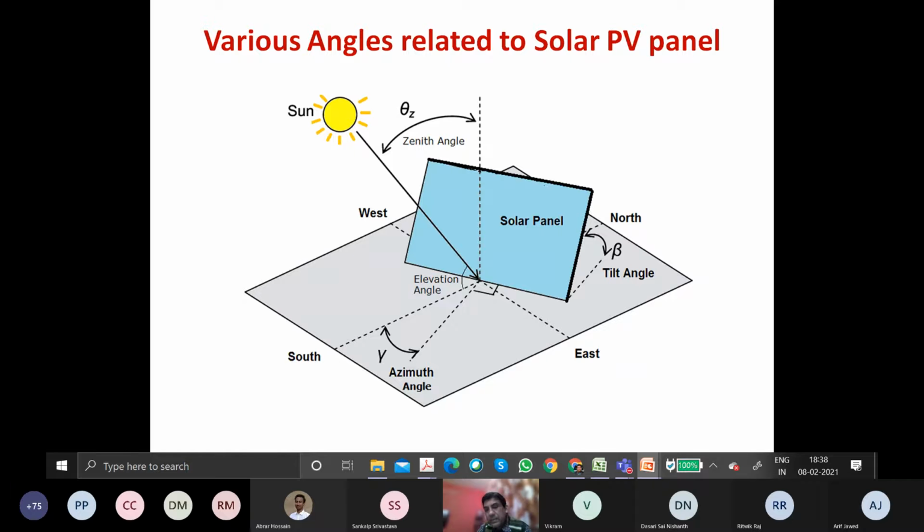right? And that leads to research and development in different materials. The material may be a single material, it may be a compound material, it may be a different material across the PN junction. So it is the same PN junction, p type, n type, but the material may be different on p type and n type, so that different energy of photons can be absorbed. So there is one variety of solar cell called a tandem cell, or you can say a cascaded cell. It is a layer of two or three different types of materials, and each one has a different band gap energy.